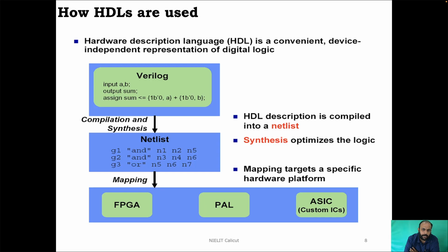By concurrent, I mean every single line you write in Verilog gets executed concurrently or in parallel, except certain lines which we deliberately write inside a procedural or a sequential box. This is very much in line with the working of hardware, the concurrent nature, which is not really part of the normal programming language.